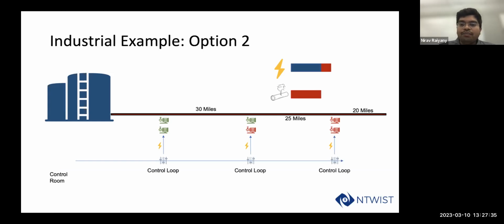However, when you look at the energy consumption, the first configuration is costing you more, while the second configuration is consuming less power. But on the other hand, the power consumption is not the only thing that you look at, because when you are operating this pipeline, you also have to keep in mind the pressures that you are ending up with when you are making certain selections, because high pressures or fluctuations in pressures could damage your pipeline, it could result in leaks, it could basically burst your pipeline. So there are lots of things, and it could ultimately reduce the life of your pipeline, which again comes to the capital cost.